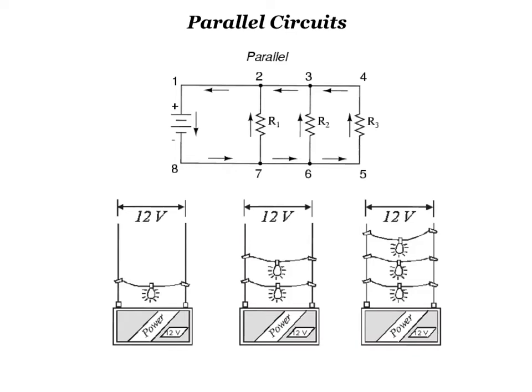The current comes out of, this picture here is showing direction of charge movement, right? Current we count flowing the other direction. So the current comes out of the positive side of the battery and comes to a junction, at which point some of it splits, goes one direction through R1, other direction through R2, splits here at this junction. Some of that current goes through R3. All that current comes back together after junction and back to the battery.